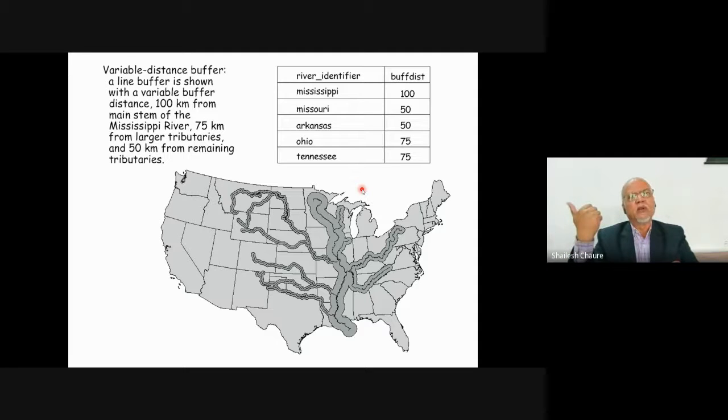So in that case, what will you do? You will just select one particular category of road, say national highway, and then create a buffer. Then you will select state highway, then you'll create a buffer. Like that, you will go on. So if you have 5 types of roads, you have to perform 5 different operations. But we can do it in a different way also.